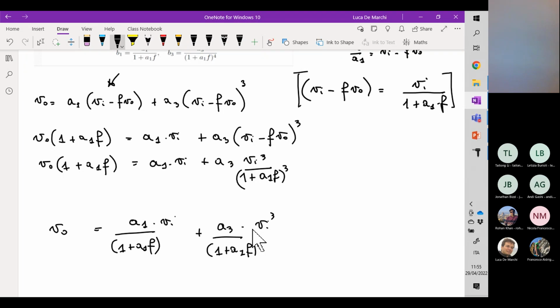So basically, the line corresponding to this quantity here, 20 logarithm base 10 of 1 over f, is our new 0 dB value. It is the value which corresponds to the amplitude of T of j omega being equal to 1.